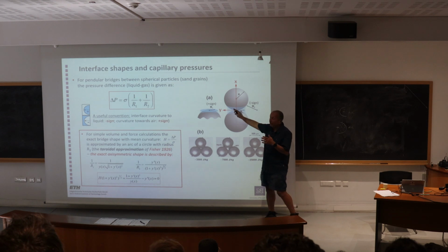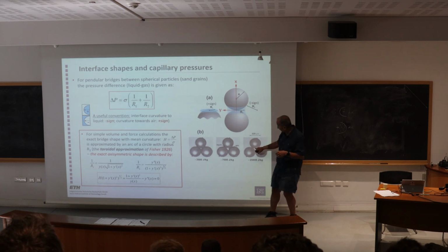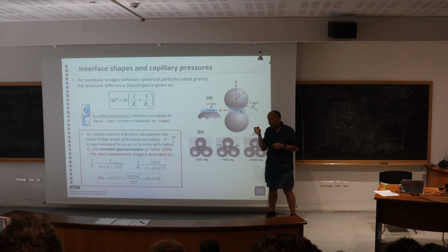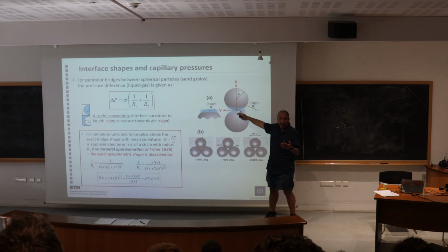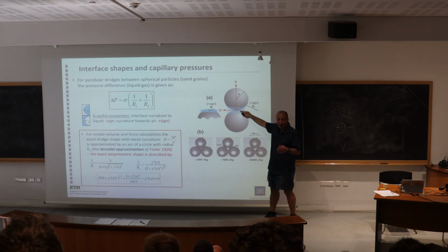You may be familiar with this, actually these are images. You may be familiar with the formation of pendular rings of water around these grains. Especially in unsaturated sand, these are very conspicuous, you can see them. And you can apply the Young-Laplace equation, or the Laplace-Young equation, to calculate what would be the pressure inside these